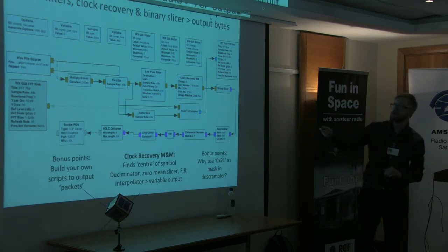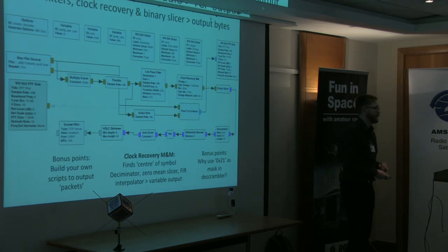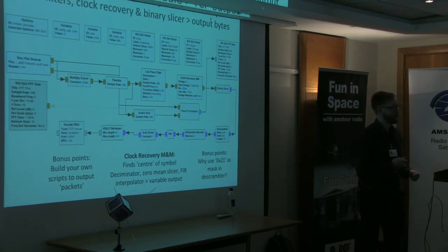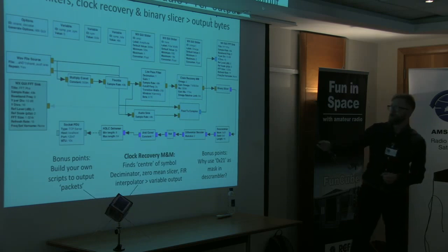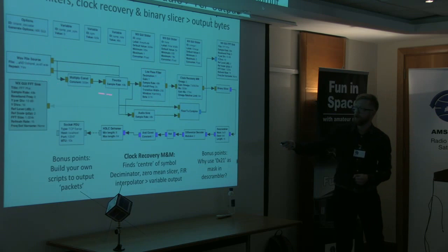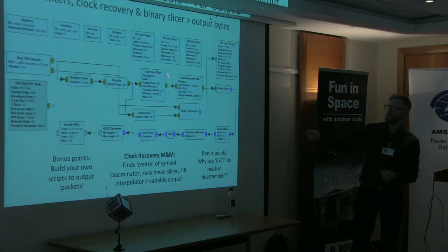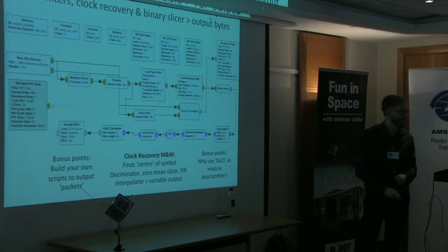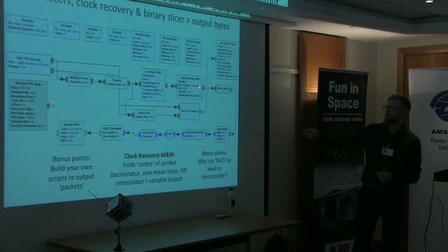And when we start building up our very own TNC, you will need to think about how you decide what is a 0 and what is a 1. How do you define what those things are, whether it be tones or different types of signals? When we pass our signal through, in our baseband audio, we start to look at filtering it down. And these are sitting on a slider, so I can change the filter widths, etc.